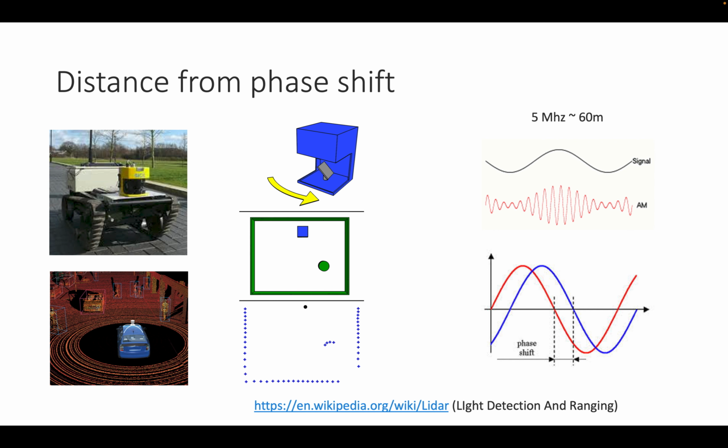An important class in robotics is measuring distance with a laser. These are devices that were originally built to protect industrial installations from humans entering them. They would create what was known as a light curtain by emitting a laser ray, as you can see here, at very high speed. If a person walked into this laser, we would be able to detect this, and these devices would physically shut down the power to the plant. When they came out, roboticists very quickly adopted them to allow a robot to localize itself in an environment, map it, and then navigate it.